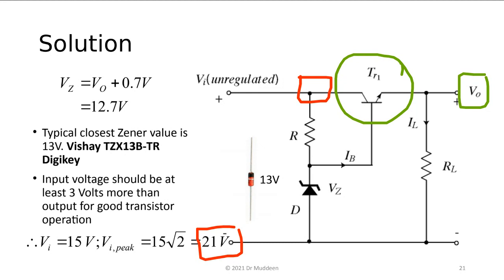It's an interesting decision. If somebody said, okay, 15 volts DC, I could go backwards. If 15 volts is the peak that I want, I could work out the equivalent RMS and give myself a little bit extra. If you told me you will use a 12 volt transformer, which gives me about 16 volts coming out here, I would agree with that, because you're still more than the 3 volts across the transistor for it to operate. So I have no problem with that.